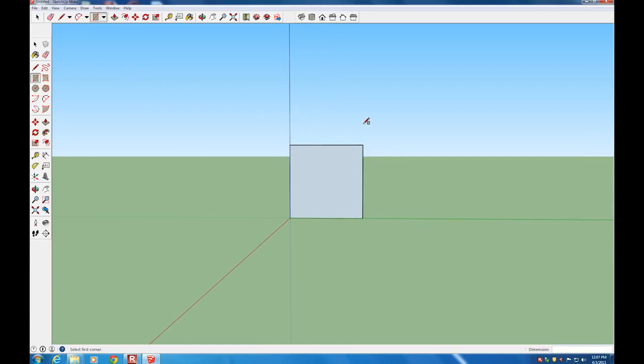So now we're going to add a back to the chair. So I'm going to go over and click on the Line tool and start from this corner point. Notice it highlights the endpoint to show that it's inferencing off of that. Draw up vertically 0.5 meters. So draw in the direction you want to go, type 0.5, and click Enter. And then from the end here, we're going to go over 0.1 meters, and then straight back down to the base.